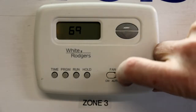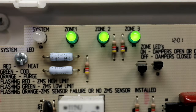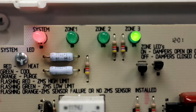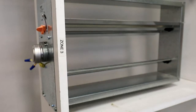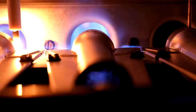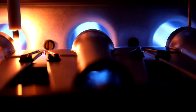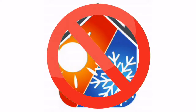If Zone 3 now calls for heat, then the damper to Zone 3 will open and the other 2 zones will close and the furnace will start. As is obvious with this type of zoning system, it is not possible to simultaneously heat and cool different zones at the same time.